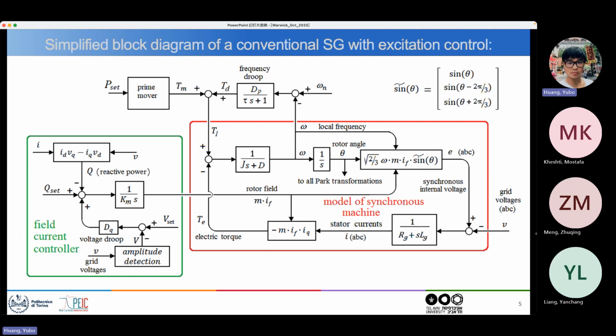And from this active torque, you have to subtract the electric torque, which is due to the currents flowing in the stator windings. And the difference will act on the rotor in the sense of the mechanical mass of the motor, in the sense of either accelerating or decelerating it. If this difference is positive, then it will accelerate the rotor.